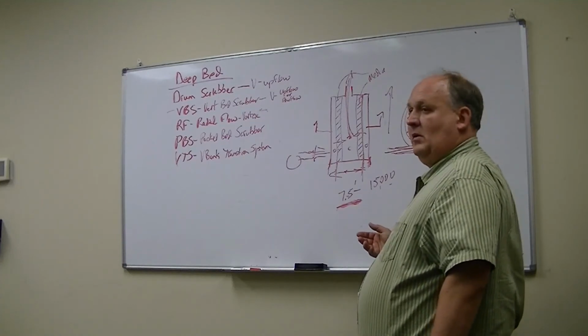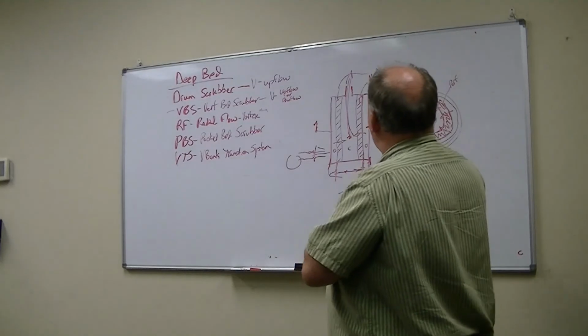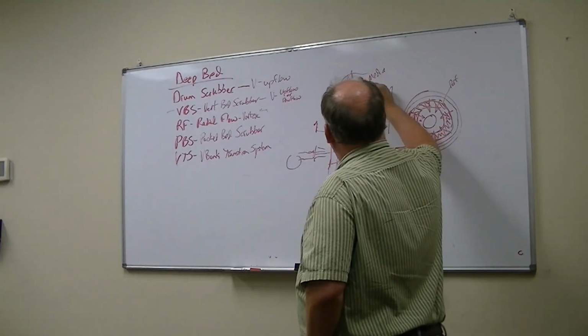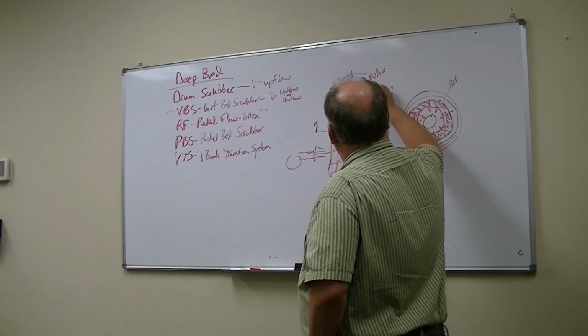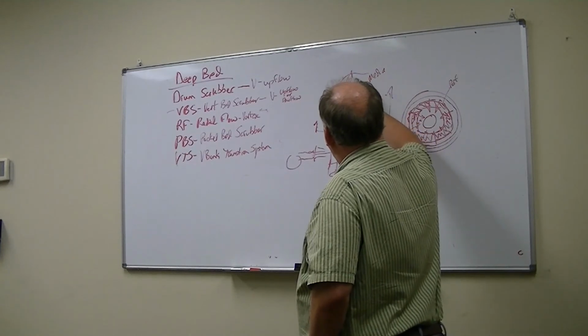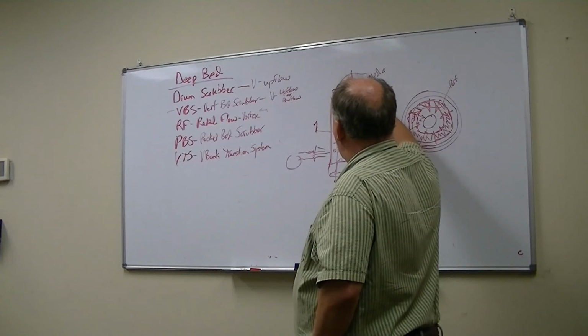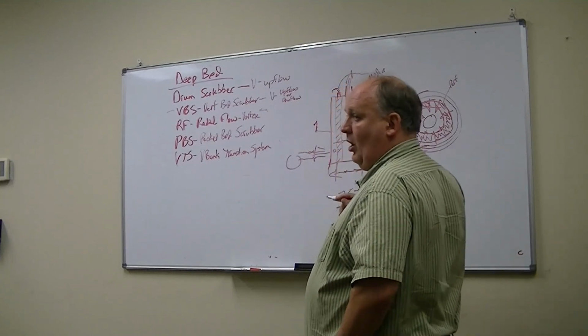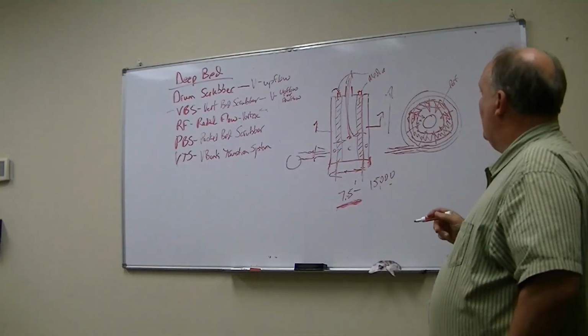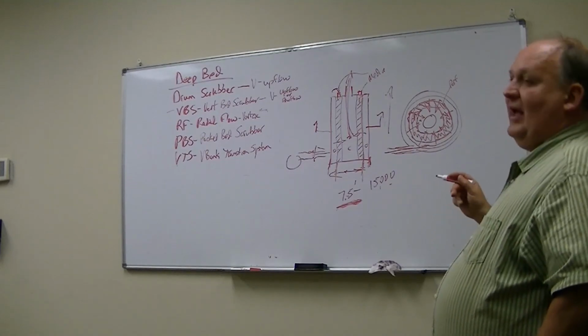So, how do you change the media in that? Yeah. So you change the media out because up on top there's some type of fill chute here that you go in and you climb up on top and you vacuum the carbon out, the absorbent media out, and that can be a little problematic.